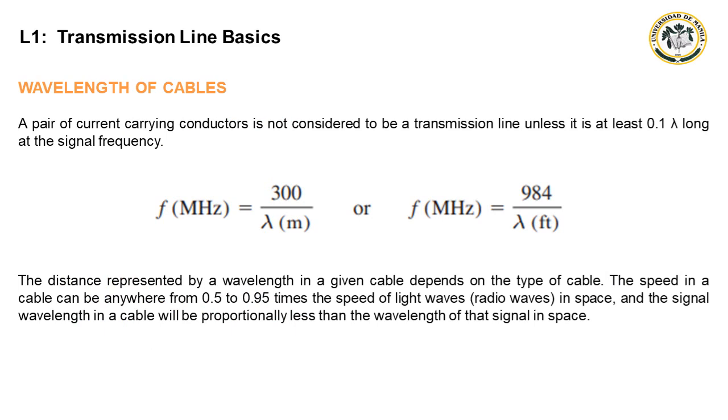At low frequencies, the transmission line acts as a carrier of AC voltage. For these applications, the only characteristic of the cable of interest is the resistive loss. The size and electrical characteristics of low-frequency lines can vary widely without affecting performance. An exception is conductor size, which determines the current carrying capability and voltage drop over long distances.